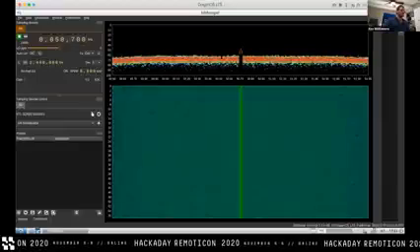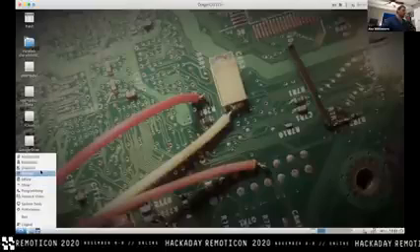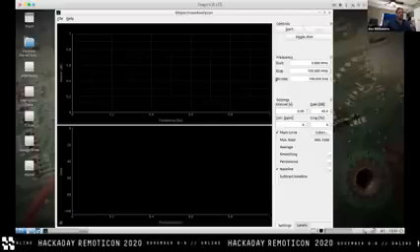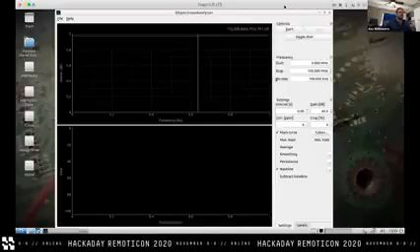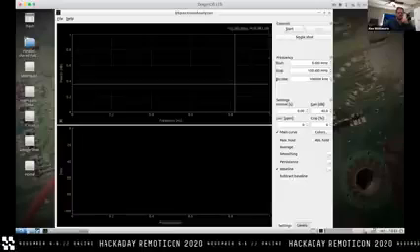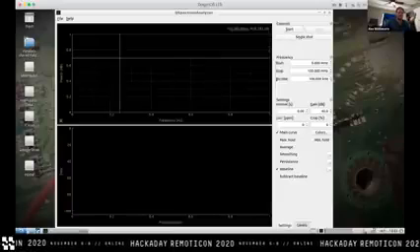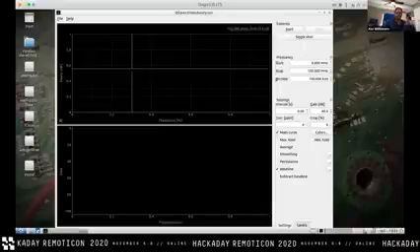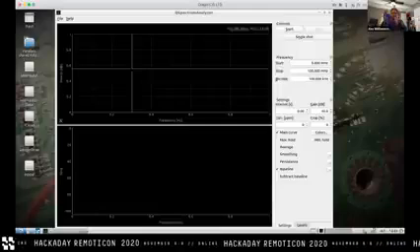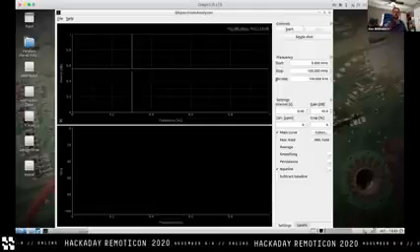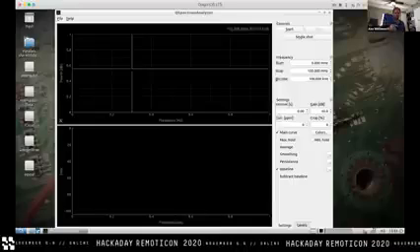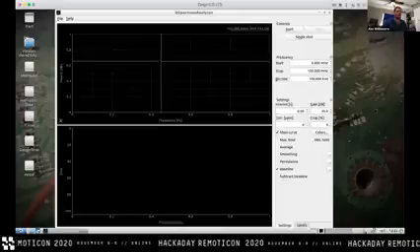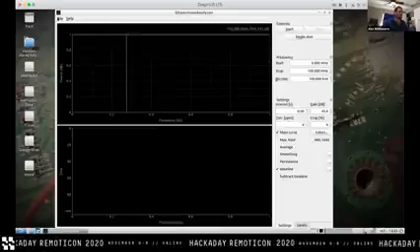Well, let's close down SDR Angel because it's not going to help, and let's fire up Q Spectrum Analyzer. Q Spectrum Analyzer is a program that tries to approximate a swept spectrum analyzer using real-time SDR devices. Effectively it does the same thing the RSA did in that mode, capturing a chunk, capturing a chunk, capturing a chunk. It doesn't do the entire digital phosphor where it captures a gazillion samples of one chunk. It just captures one and moves on. But it does accomplish our goals somewhat nicely.